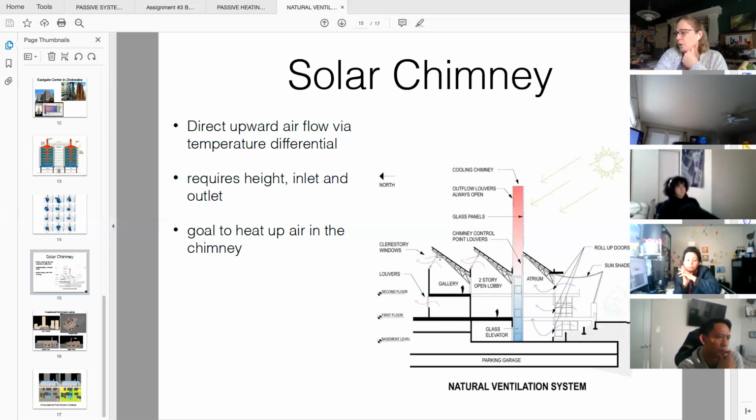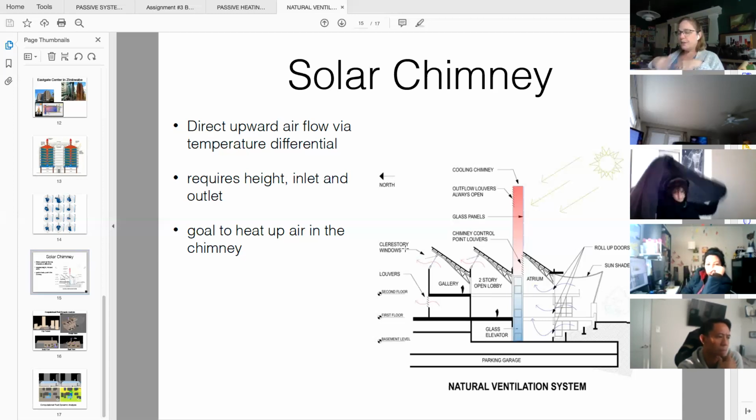The same thing with the clerestory windows: these do actually close, and that's mostly for rain protection. But if this gallery here up at the top starts to get cold, by just closing that window, there won't be any place for the cool air to move to. So it'll still heat up in that space, but then the warm air will stay in the space.